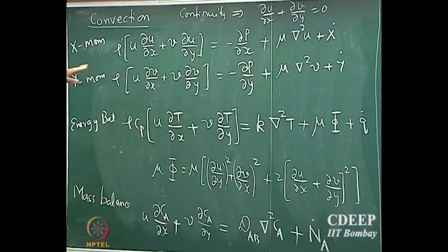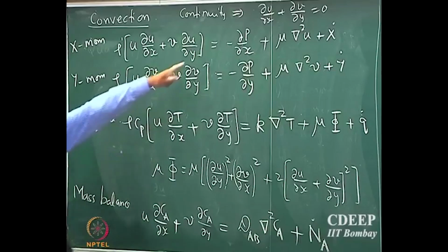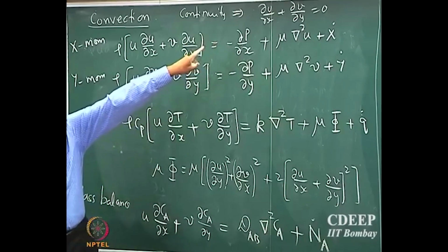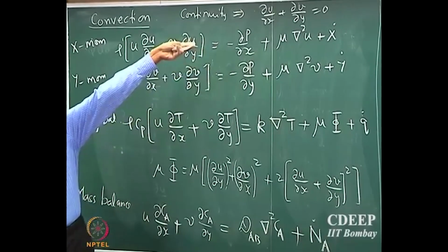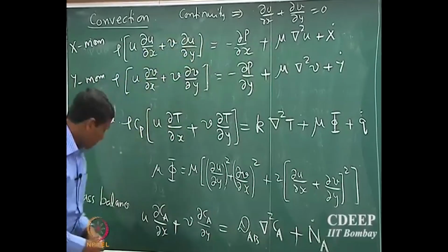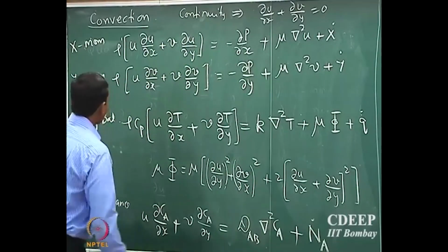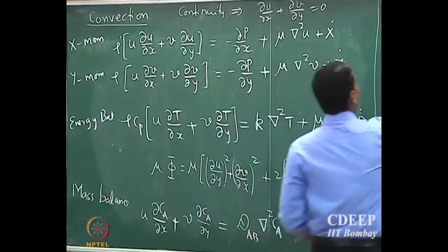So we really don't have to solve for the continuity equation because the fluid is incompressible and it's a steady state system. We are looking at a steady state incompressible fluid, so the continuity equation will always be satisfied. So you don't have to worry about solving it. Okay. So all we will have to worry about is solving these 4 equations.